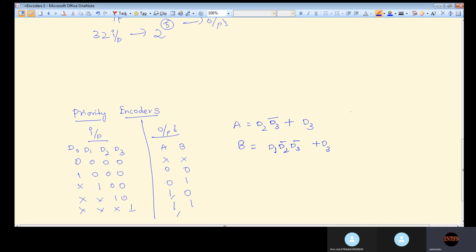According to this logic equation, we can design the priority encoder. But what is the priority encoder? So it is a logic circuit. Okay. Priority encoder is a logic circuit which responds to just one input, to just one input in accordance with some priority system.